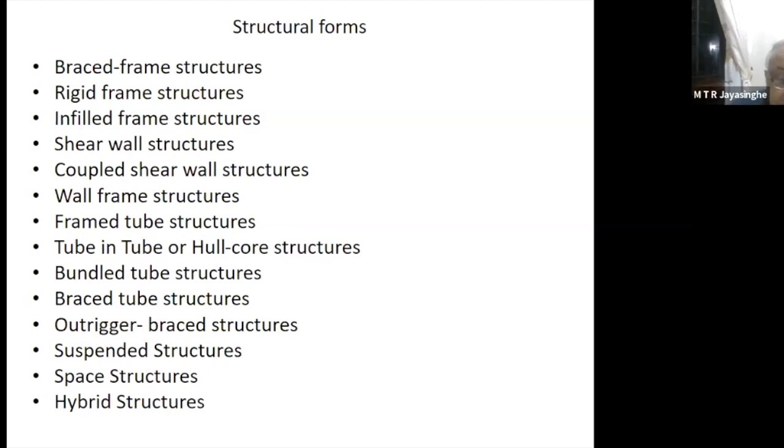Okay, if a building is supported on end-bearing piles through peaty soils in the upper layers, how do we transfer the lateral loads to the ground? Yes, you have to consider it like a table. You have one leg not stable, but a table is very stable. So you create slabs and have a thick beam-based connection for all the pile caps. If the pile cap is 1.5 meter deep, you will have a connecting beam of another 1.5 meter. The moment you have a connecting beam of 1.5 meter, then it's like a table. And there are so many piles, maybe 100 piles, connected everywhere.